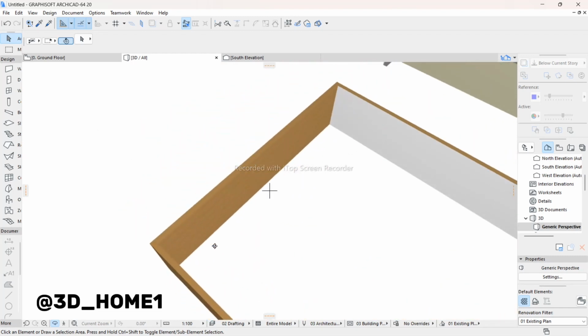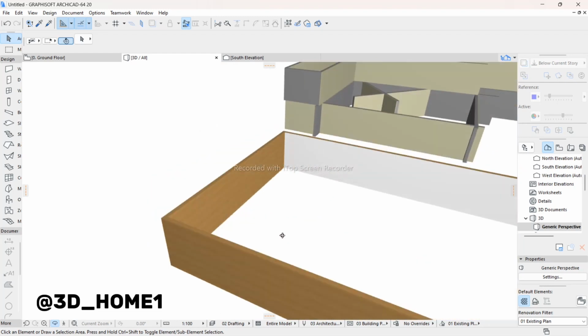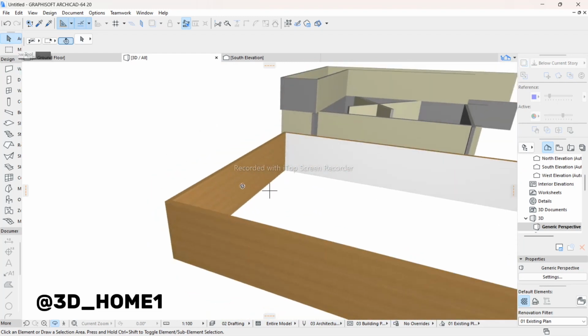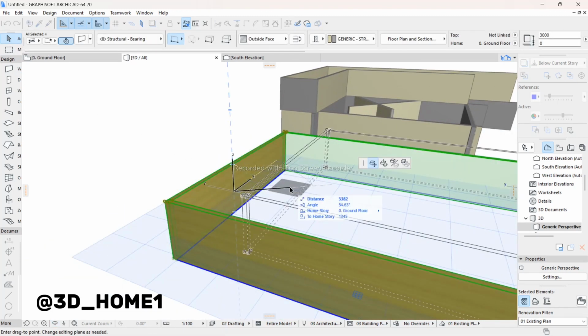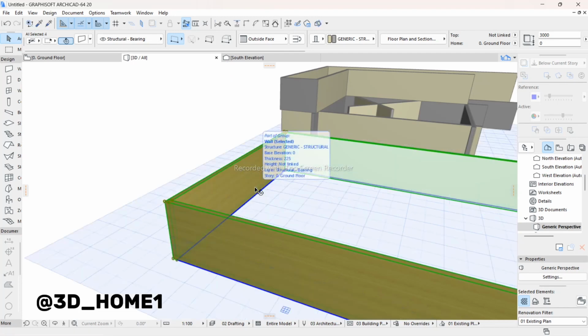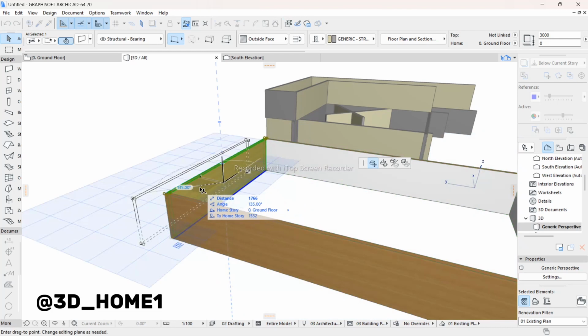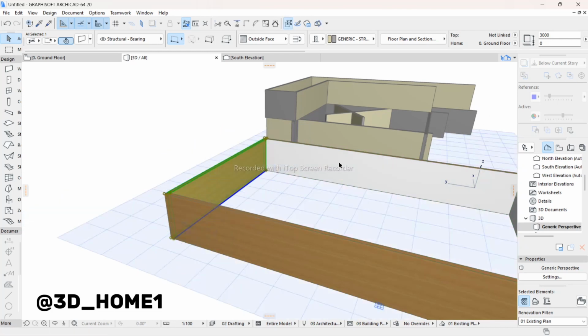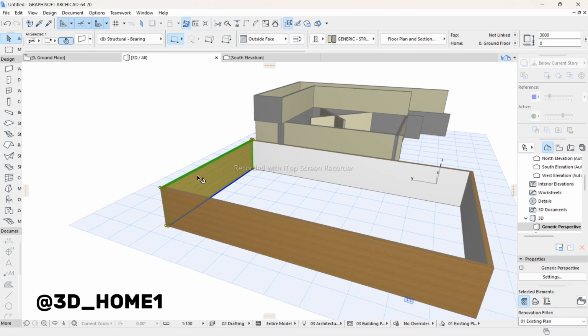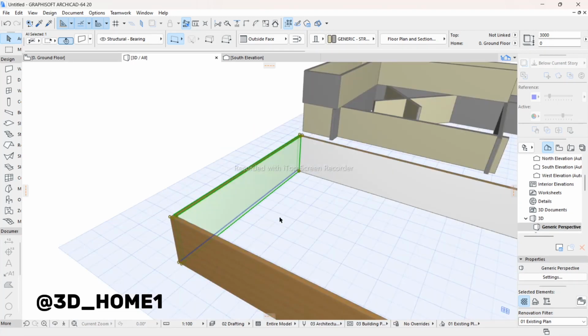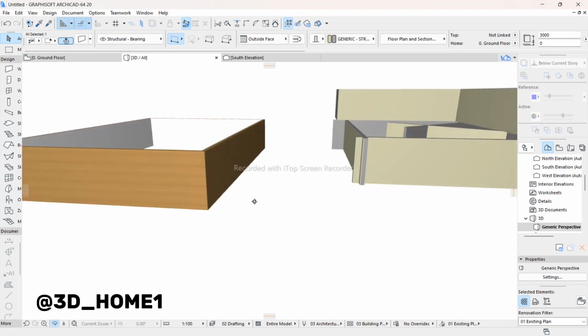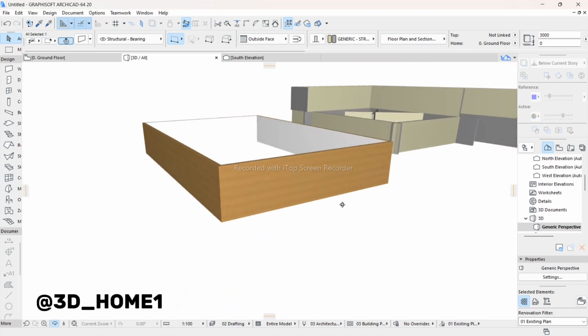So what will happen now is we'll click on the wall. Let's escape this orbit. Click on this particular wall, only the wall. But before then, let's ungroup the walls. Click on Alt G, and then select this particular wall and then press P to automatically flip inside. Okay, let's stop. Let me show you how to just add a door.